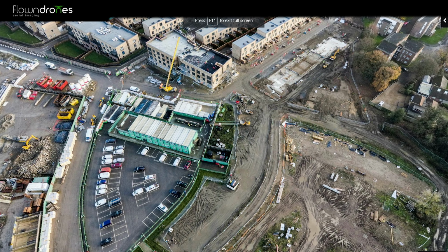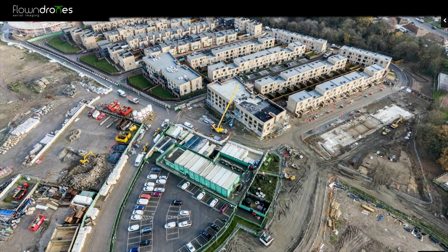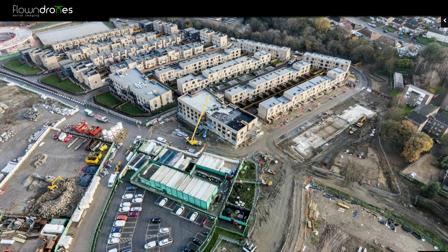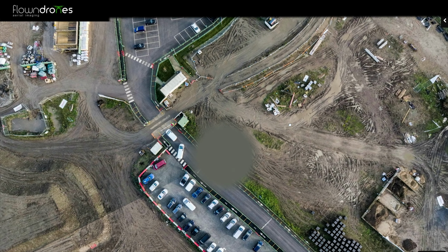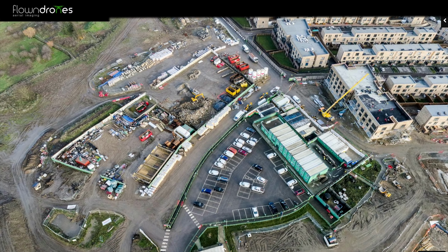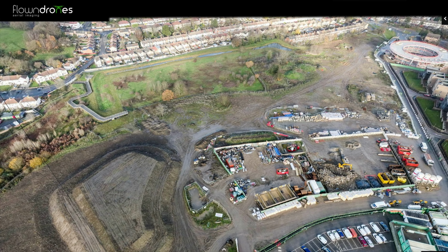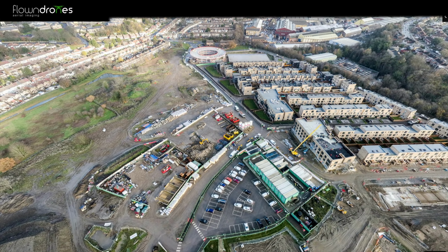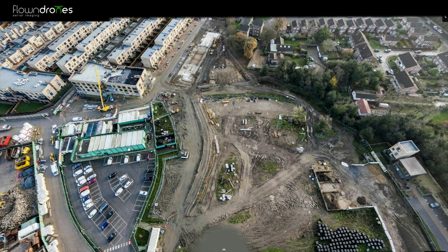The next option we have, which are more simple, are the new 360 degree photos, which can be taken from the same point every month with the drone using the GPS again, and they allow you to move around and have a look around the site just from one position. They again have to be flown on fairly low wind days. With high winds they won't work as well. You can zoom in and zoom out. They're not as accurate as the models, but they're a lot quicker and cheaper to make, and allow you to have a good look around the site.